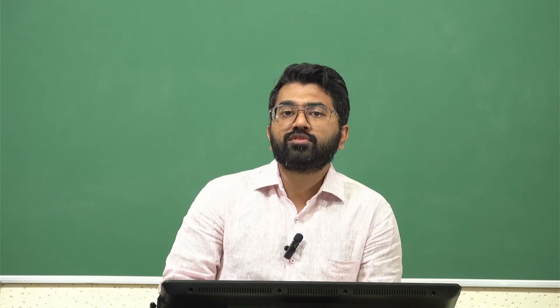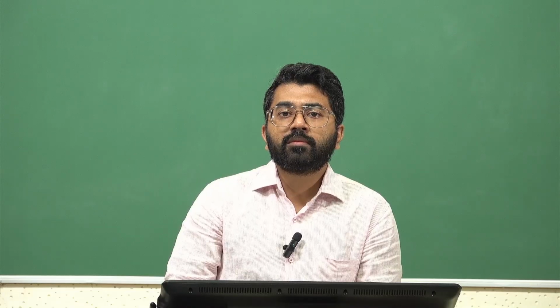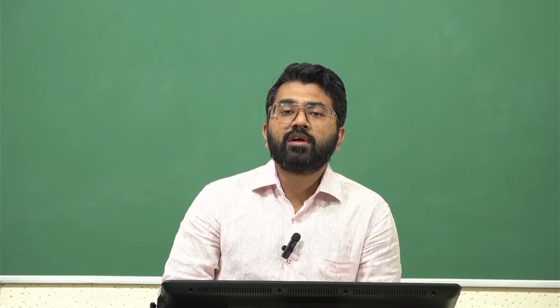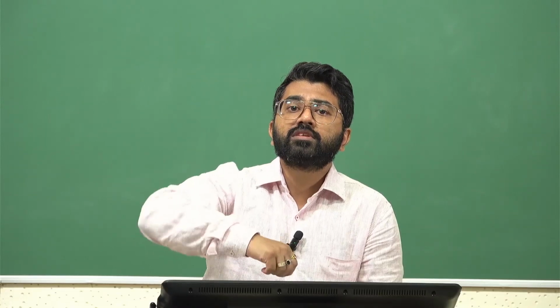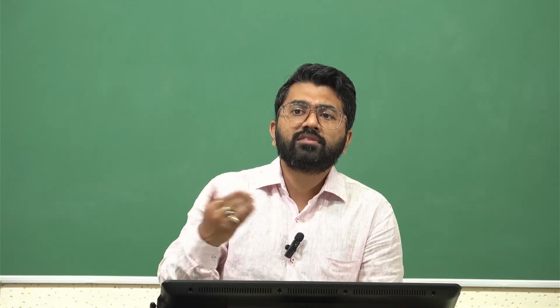test will automatically stop. Another thing to note is any kind of tests, be it tensile, compression, or the other tests which we are going to discuss, have to be conducted at least 3 times, not necessarily on the same specimen. If you have taken it up to destruction, you cannot be using the same specimen. Take another sample of it. Take 3 different samples.